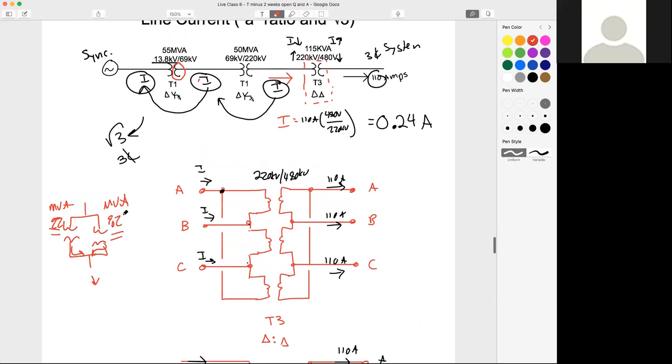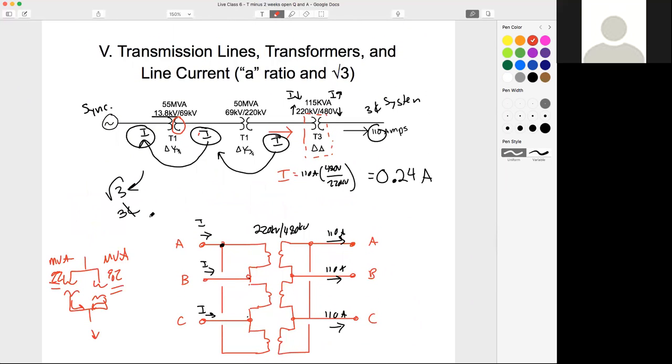But no, in normal conditions, I'll say ideal normal, right? I'll cover my butt. In ideal normal conditions, your percent impedance is going to have no effect on your current and your voltage from primary to secondary, right? Because the only thing that has an effect on that is what? Is your ratio. That's all.